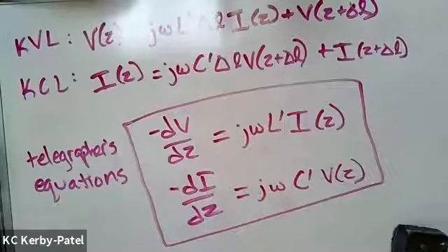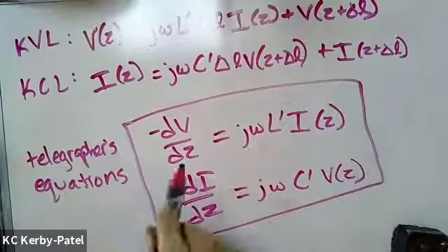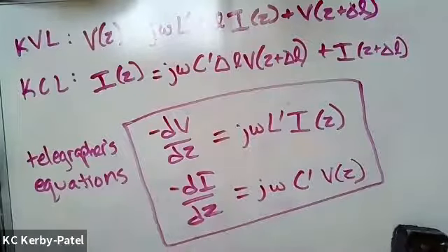Without it, it was kind of impossible to understand how telegrams worked, because again, we're talking about the wavelength being really long. So if you want a long distance telegram, those wires have to be many kilometers long. These telegrapher's equations describe how voltage and current behave on those really, really long transmission lines that connected telegrams from one place to another.